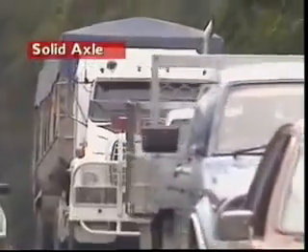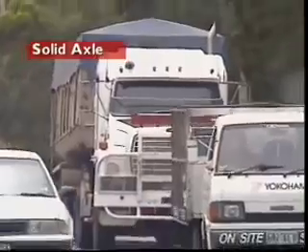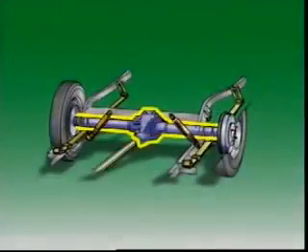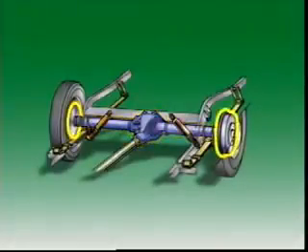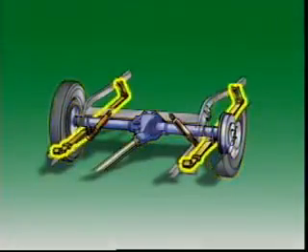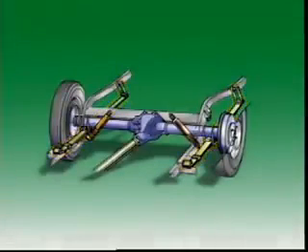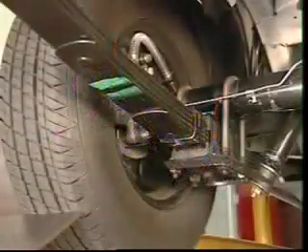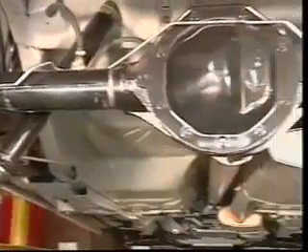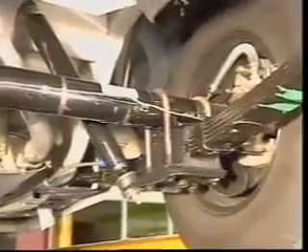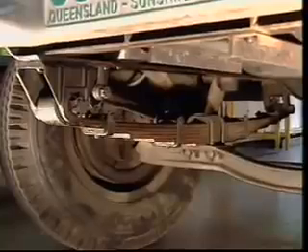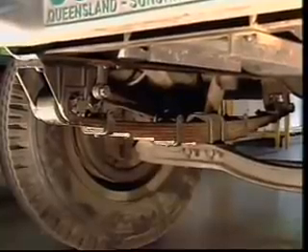This section examines the solid axle or beam axle. The solid or beam axle provides a simple means of locating and mounting the hub and wheel units. Together with leaf springs, it forms an effective non-independent suspension system. Similarly with coil springs. It is still used in the rear suspension of many front-engine rear-wheel drive cars and light commercial vehicles, and as the front suspension on many heavy commercial vehicles.